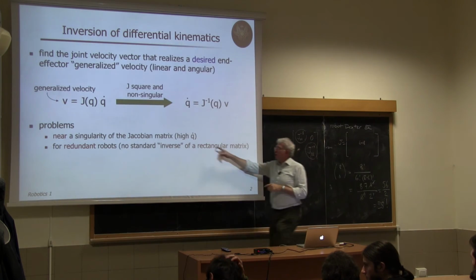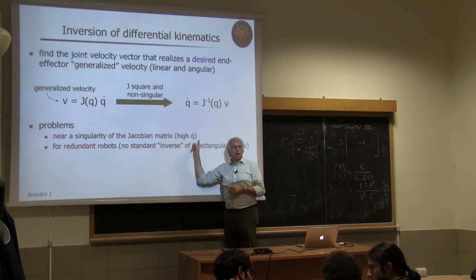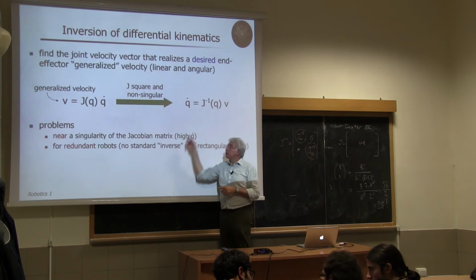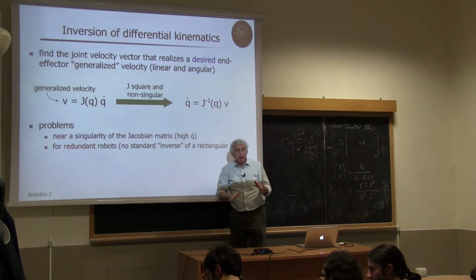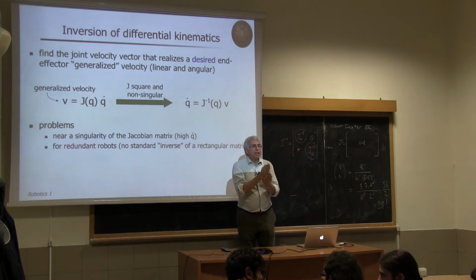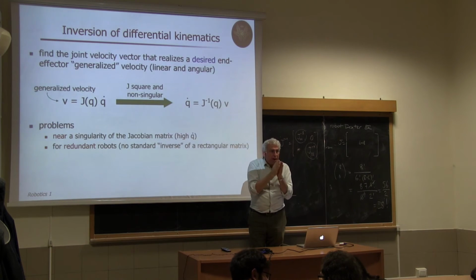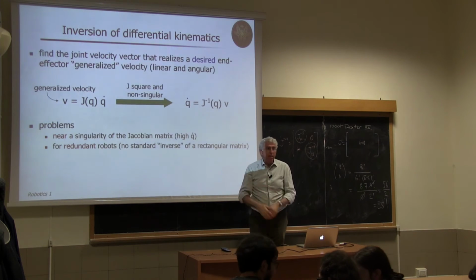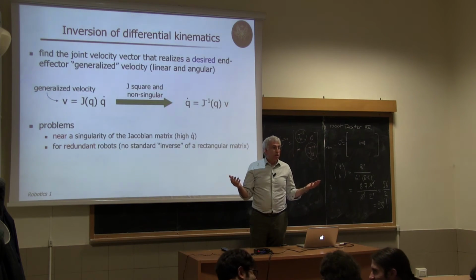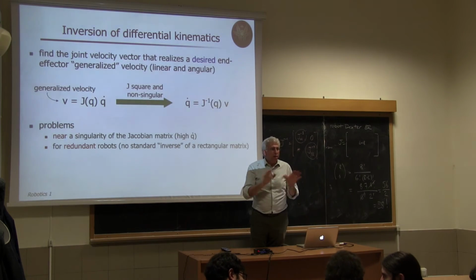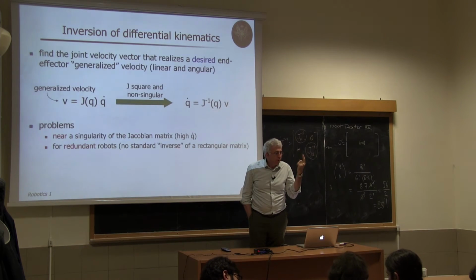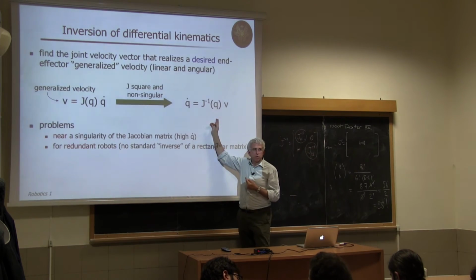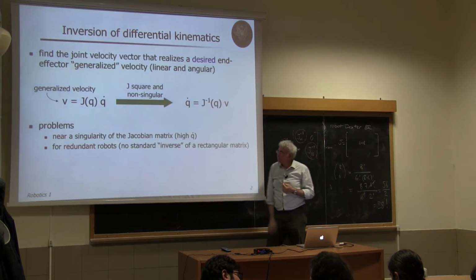So high q dot, how can I discourage such results? Especially because I can invert the matrix anywhere except exactly in the singularities, but still when I'm very close, I can invert the matrix, but I have this result, large q dot. So how can I prevent this, even if I have only one solution? Because this is the unique solution, as long as the inverse exists.